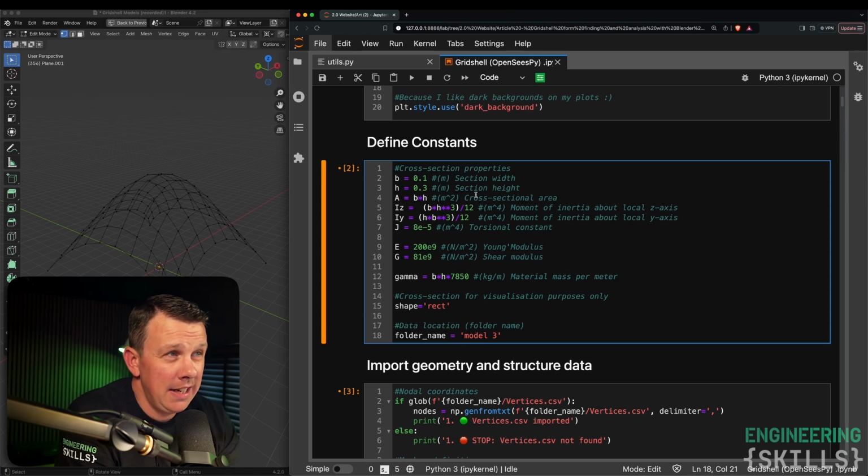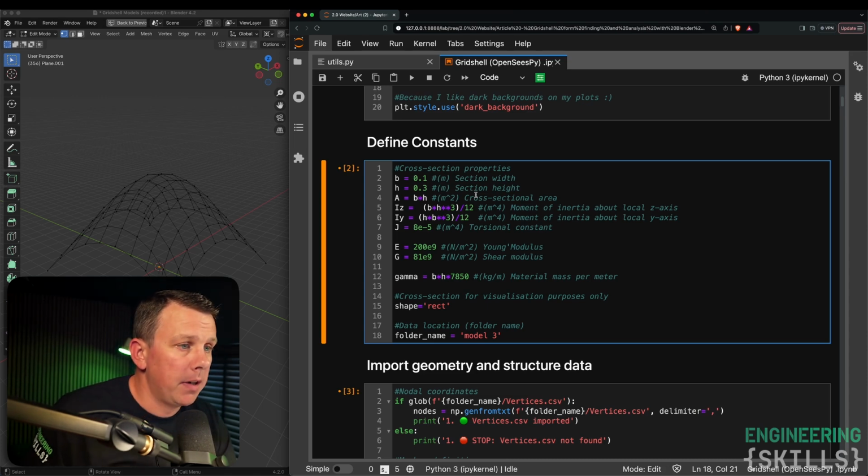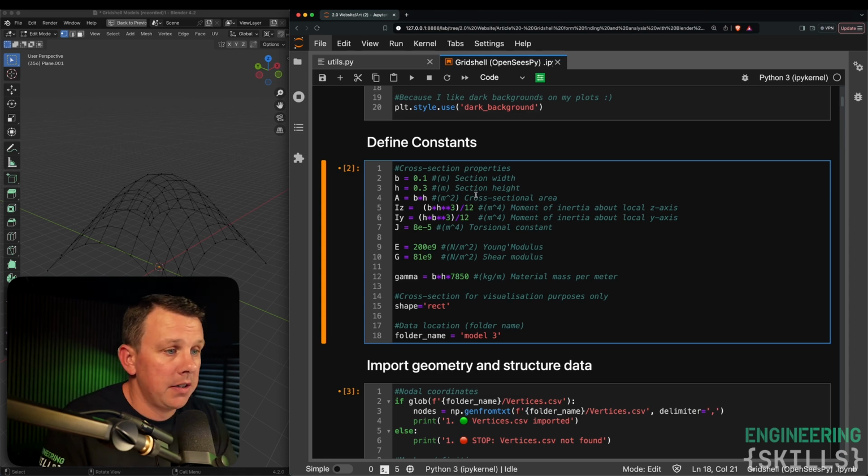And of course this actually isn't a bad thing, because this is much more in line with what we would actually expect in this structure. If we were to build this grid shell, we would never be producing pinned joints. We would always be locking off those joints, and so they would be resisting moment. And so actually the way we're simulating it much more closely mimics reality. So it's a good way to go. It's not a compromise in any way. So that's a thing that really was worth getting clear in your mind, because if you naively approach this as a truss structure, you won't get very far because the thing won't solve. You won't be able to invert that stiffness matrix.